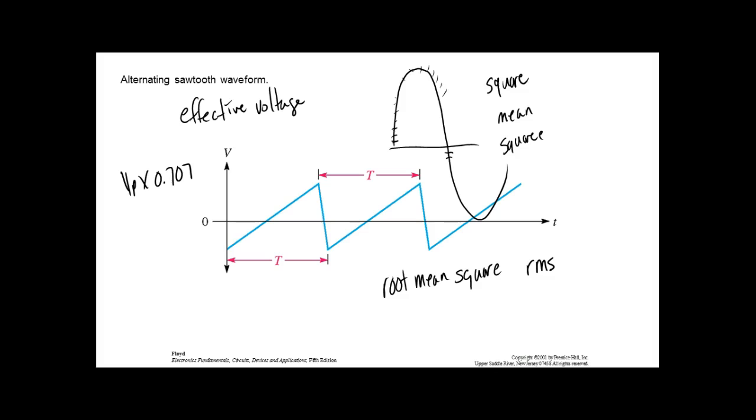You don't need that unless you're in a field where you measure non-sinusoidal waveforms, like variable frequency drives that run AC motors. Those generate non-sinusoidal waveforms. So this guy here would measure something, but it wouldn't be accurate, right? You understand that?